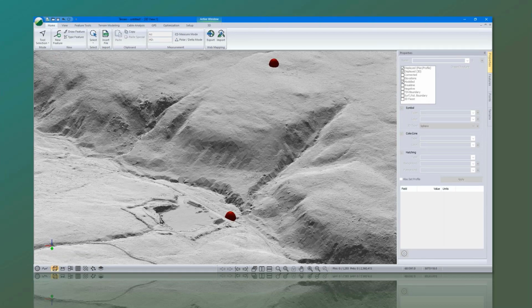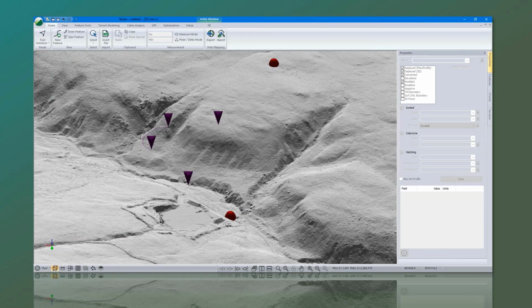So if we were in the field and we knew we wanted to go from that low point to the high point and we didn't know where to put a road, we'd probably start by doing some walking around and figuring out where our control points are. So usually things like your major crossings. If you have a switchback, that's tricky, so you usually spend a little bit more time figuring out where that should be so it doesn't cost you a bunch of money.